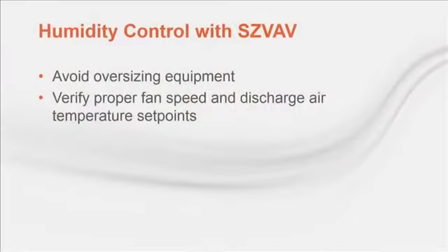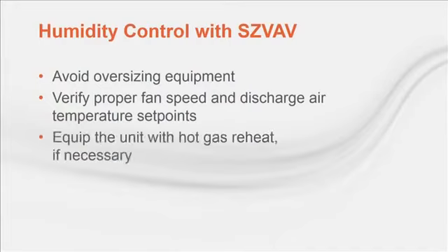So let's summarize. Avoid oversizing equipment whenever possible and make sure the equipment is being controlled properly. If additional dehumidification performance is necessary, add hot gas reheat.